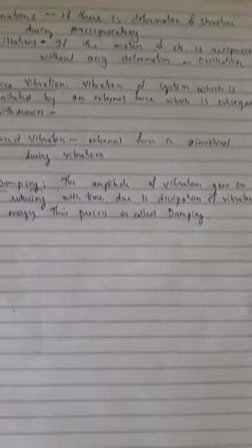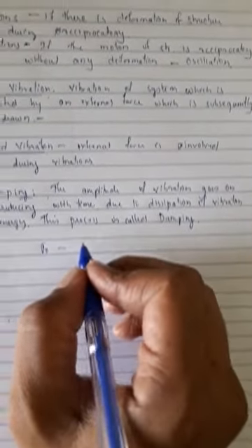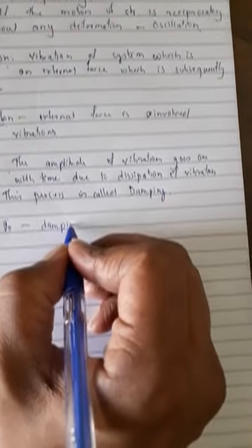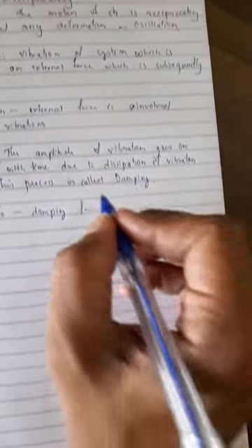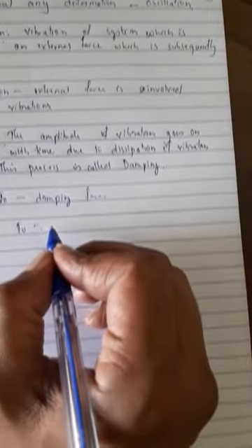In case of free vibrations, where external force is removed after initial excitation, the motion gradually evens out. Evens out means stops. Now this damping depends on a lot of factors and it is very difficult to quantify. It is very difficult to measure the damping. Hence, damping of this system is represented by a viscous damping force. Let F naught be the damping force. This F naught is equal to C into X dot,